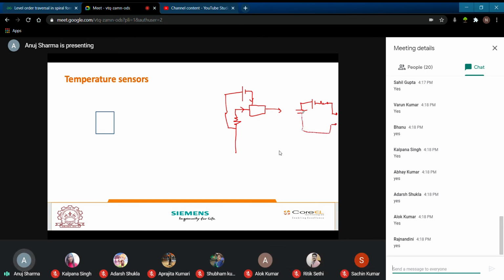Okay, let me repeat this. Your RTD will have a varying resistance. A voltage has been applied across this resistance. The resistance will change because of the temperature. This will provide us an altered voltage. That altered voltage will be amplified or processed through the transmitter so that it can be compatible with this current loop. Through this current loop, your current will be altered with this altered applied voltage. And through this altered current, you are going to sense the change and calibrate it.